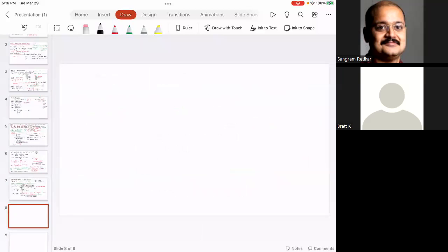So here is a slightly alternate approach. So note, to find tooth error action, pitch line velocity Vp is 1.3 meters per second. Refer table 28.6.